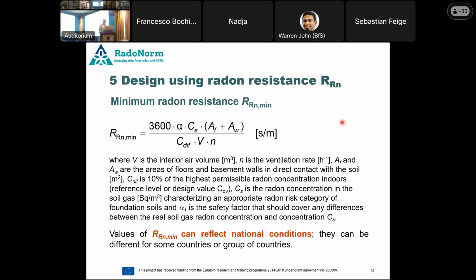Yes, of course. Yes, but it depends on the material properties and material composition. So high-density polyethylene membranes are resistant to soil corrosion, for example, and their durability is many years. On the other hand, for bitumen membranes or polyvinyl chloride materials, the durability is significantly smaller.